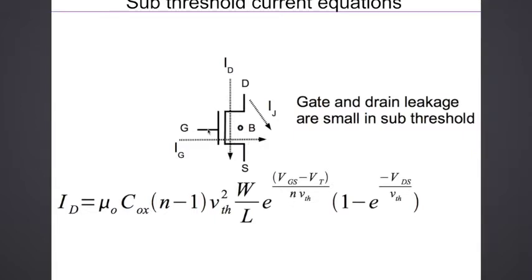And it gives an indication of how much control the gate has on the channel. Because your channel has multiple masters, including the drain, the bulk, and the gate. Right? So the potential on any of these can influence the state of the channel, and all of these can control how much the channel is inverted. So this captures that. And then you have this term 1 minus e to the minus VDS by VTH, which tells me that this current is also controlled by the VDS voltage.